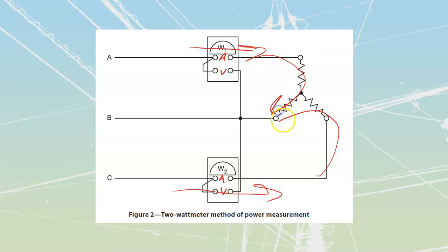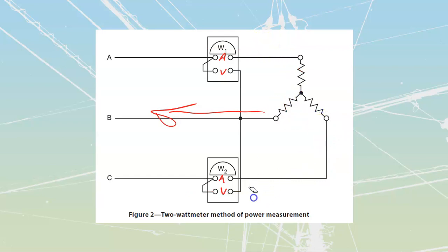We're just going to draw it like this. I know it alternates, goes back and forth, but if we take a look at this, we can see that we would be able to measure all the current going back out of the circuit, and anytime one of the other lines goes high, the other lines are going to be measuring the current flowing back out, etc. You will always capture all the current in the circuit using something like this. What this does, though, for its voltage connection is now make it a line voltage connection.